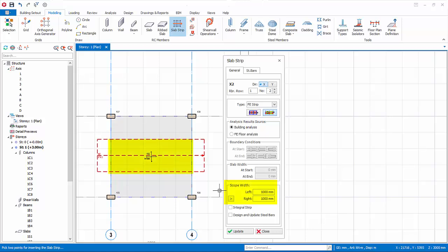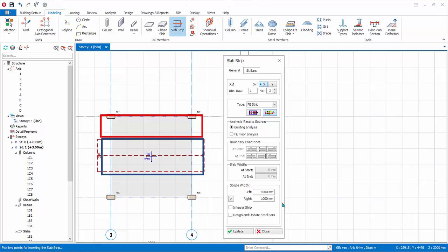The strip width does not cover the entire slab, hence, only the design moments within the boundaries of the strip will be used. In a real flat slab project, it would be more reasonable to cut several strips of different width, for example different strip at column and span area. However, for simplicity, we can adjust the width of the strip to cover the entire slab, so the design will take into account the entire boundary.